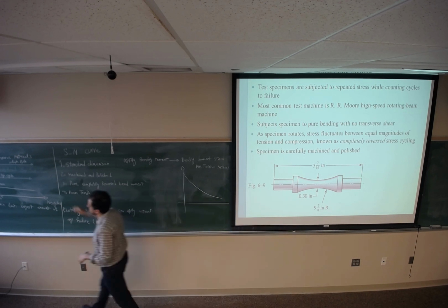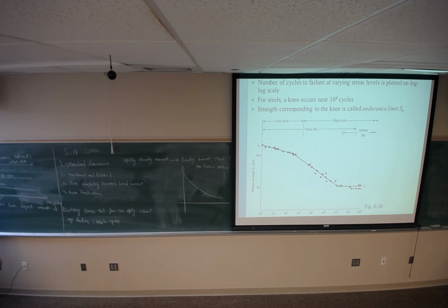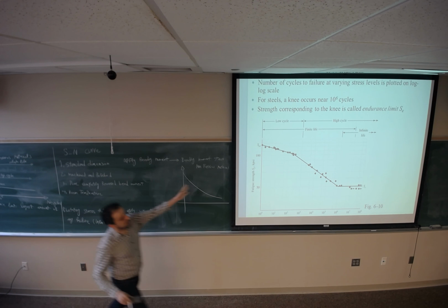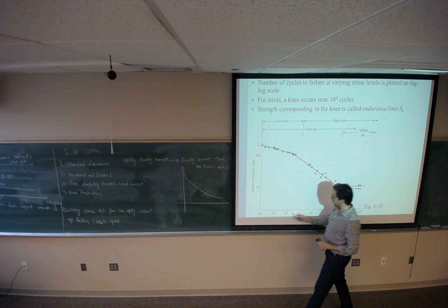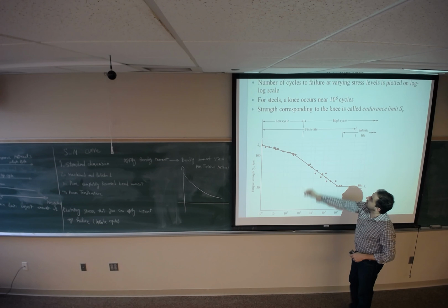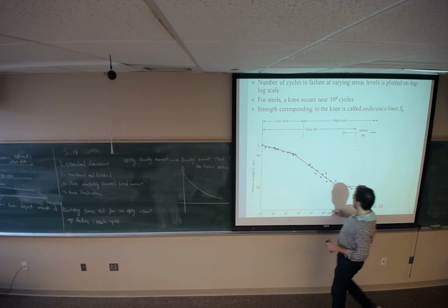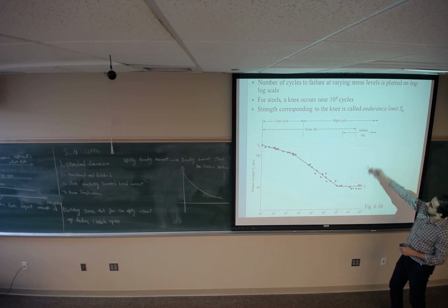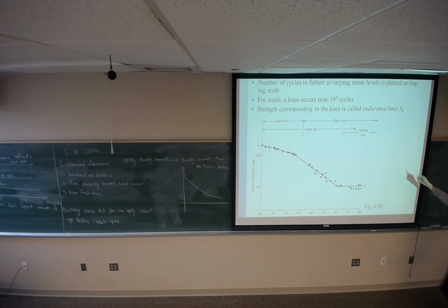For non-ferrous material, these are what we covered in the Thursday class. This graph is representing that one. Low cycle from 1 to 1,000. After 1,000 is called high cycles. And finite life is going to be defined from 1 to 1 million cycles. I mean, it's about 10 million, but no, it's about 1 million cycles. Sorry.